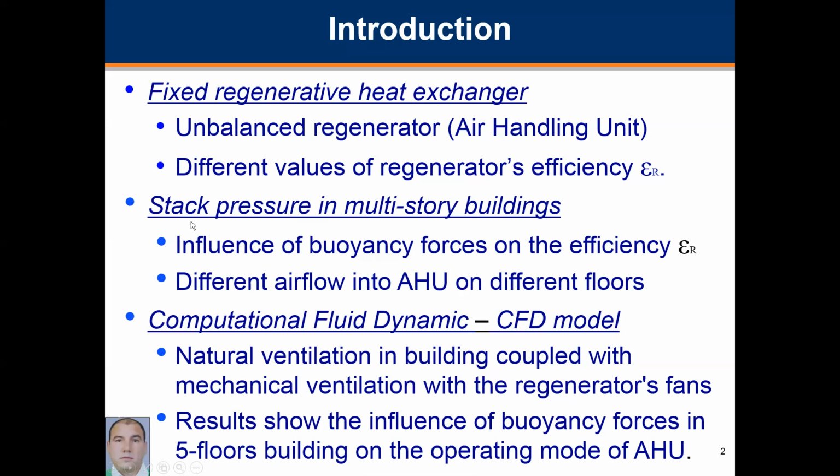The difference between the external pressure and internal pressure in the building is the stack pressure, the pressure difference created naturally by density difference from the air temperature change, or also called buoyancy forces. Unfortunately, these buoyancy forces in a multi-story building influence the efficiency of the regenerator and create different airflow into the air handling units and different air change rate on different floors of the building.